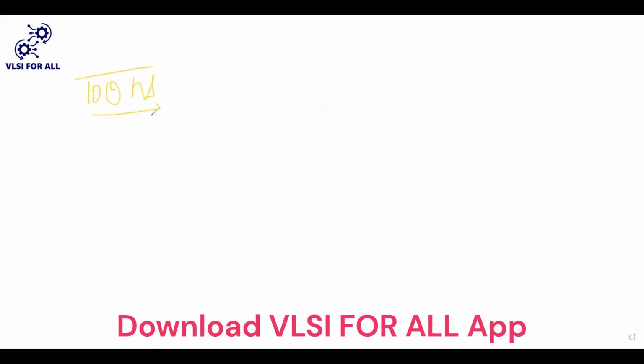Even if I'm using $monitor or $display, I may not get the required variables, because the next part of the execution also continues, and $display or $monitor will display the values based upon the complete flow of the execution. But what I want is to check the values at every step.